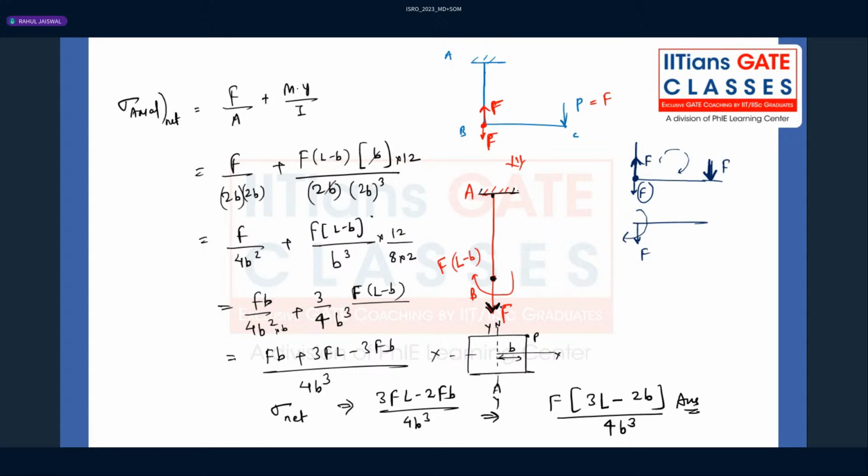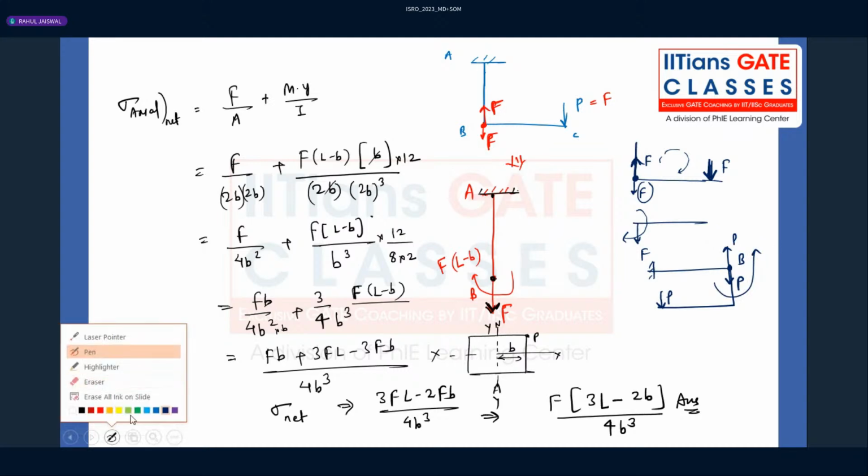Whenever you want to transfer from any load to any other load, whenever you have any load like this P, right, you want to transfer here at point B, see the joint and introduce two load like this. So one load will be coming downwards, other will create the bending moment like this. For any structure, remember, that is only the fundamental thing.